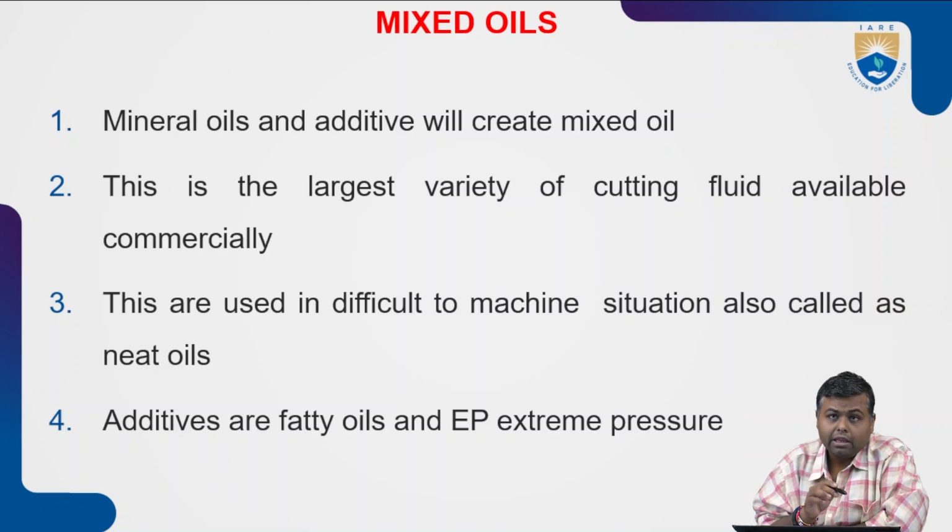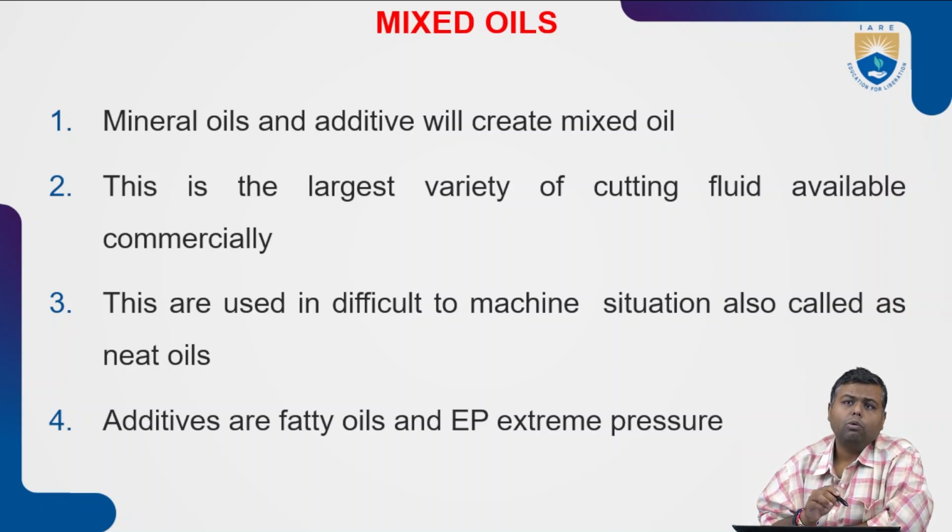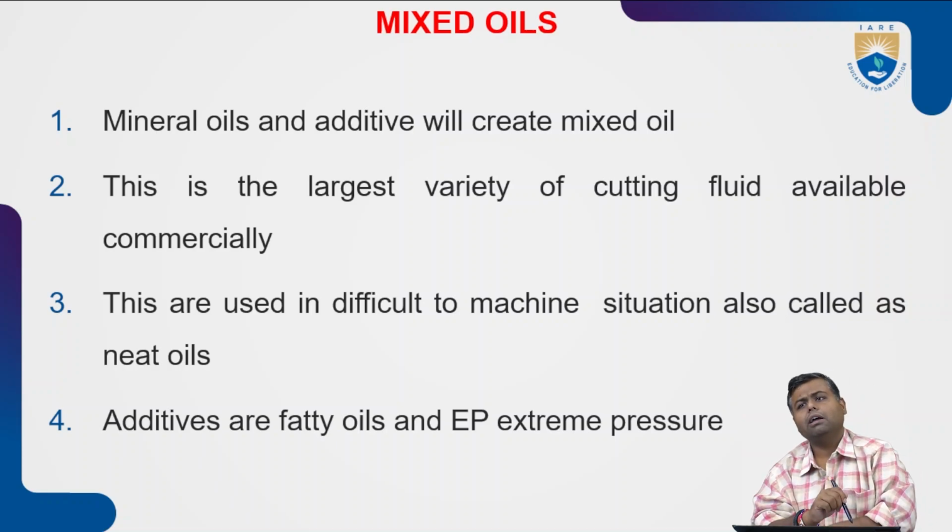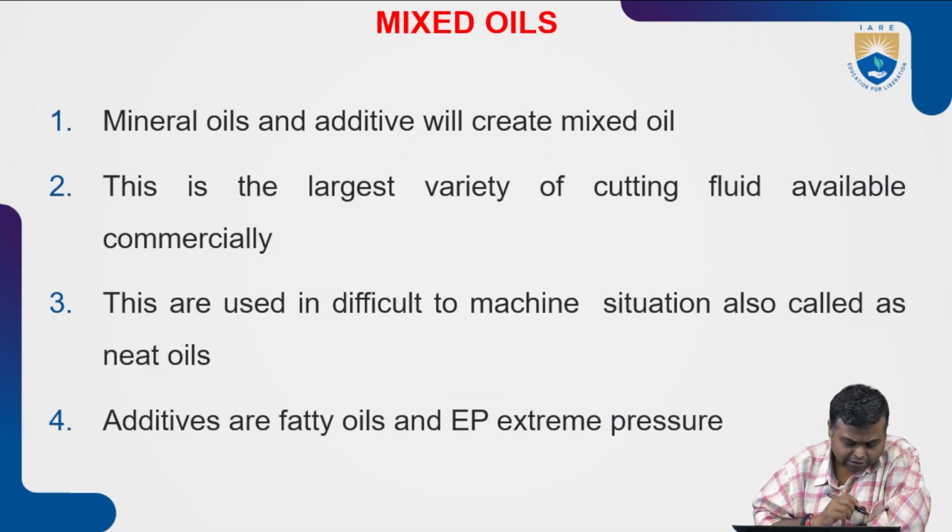They are used where you have a situation which is very difficult to machine. There it is also very suitable where you will have a neat oil application. Next, the additives are fatty oils or EP, extreme pressure oils. So EP stands for extreme pressure oils.